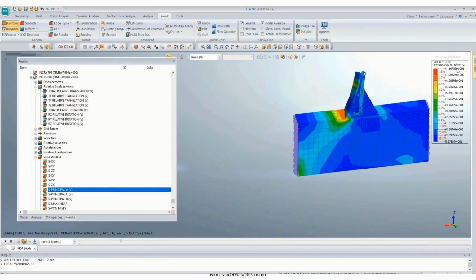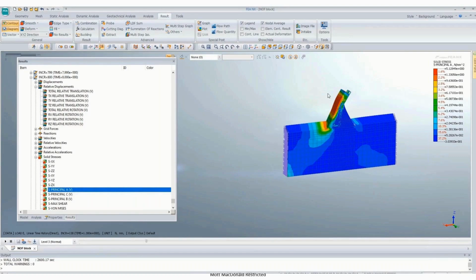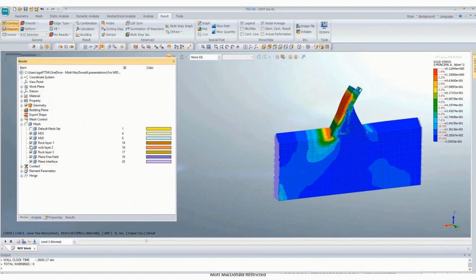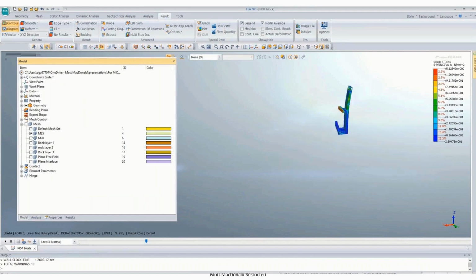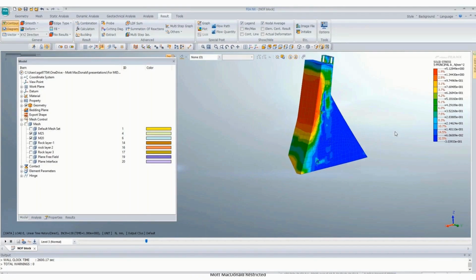Otherwise, stresses are less than 1 MPa, about 0.6. It is somewhere exceeding also in some cases. We'll see that. This is how it is vibrating. Let's stop it. We are more interested in the stresses in concrete. So this is a conservative design: I have considered a massless foundation.